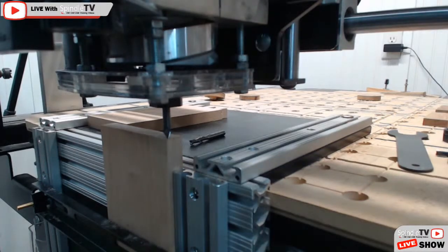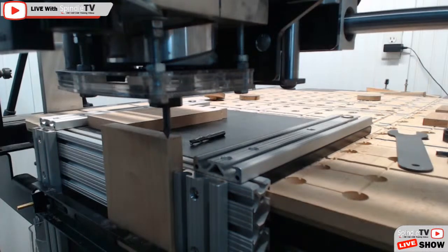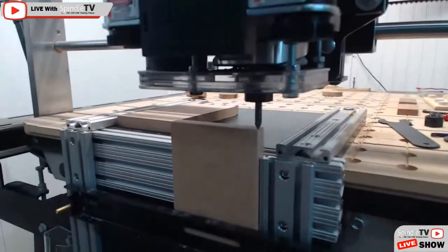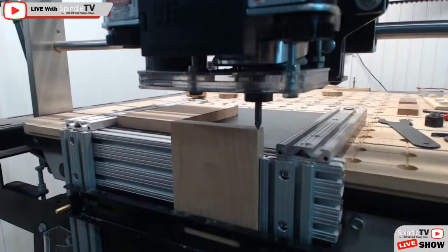All right, so my X was the only thing that I had to reset. The Y was still set and everything. So that front outside corner is going to be my XY zero. So I'm going to go ahead and zero out the X-axis and lock that in. And now we're actually going to install our cutter bit, and we're going to get to cutting. Yeehaw!